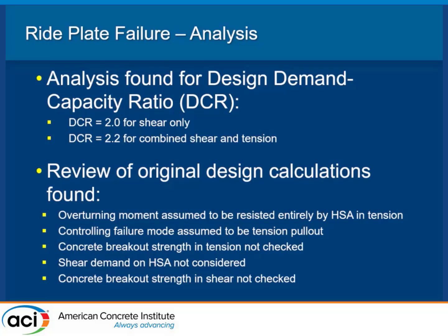If it's just running along and providing a downward force, there's perhaps just a moment, and maybe you have compression on one and tension coming up, but as soon as you try to stop, where you're producing a shear force, shear wasn't checked at all. We call these design capacity ratios when we go back and take a look at it.